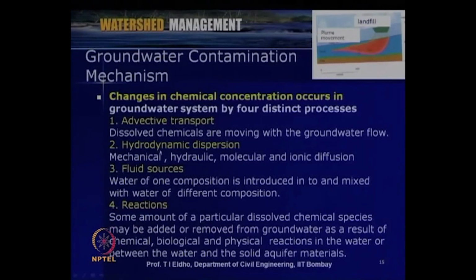And then the second one is hydrodynamic dispersion. Since the soil media is porous, and given the various ways of movement within the soil, the plume movement, or the contamination movement, hydrodynamic dispersion is another important process. This can include mechanical dispersion, hydraulic dispersion, and molecular and ionic diffusion.